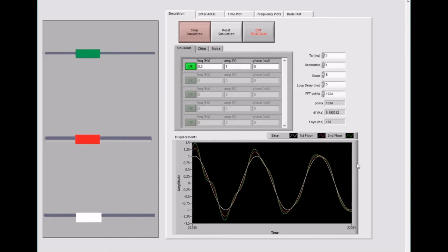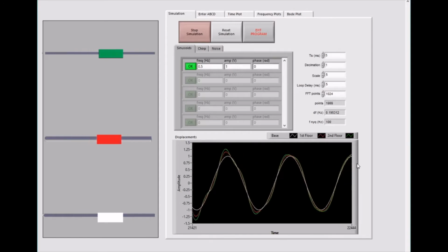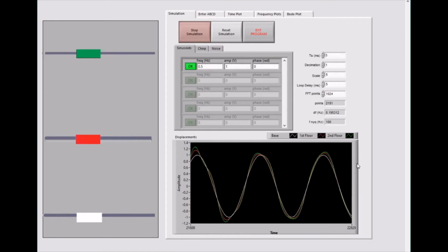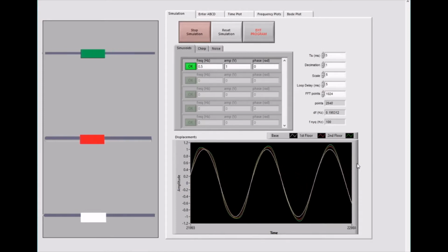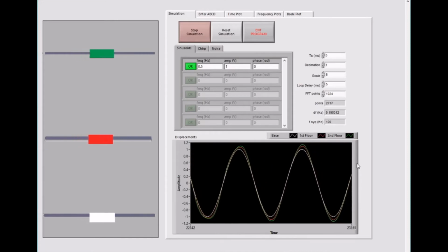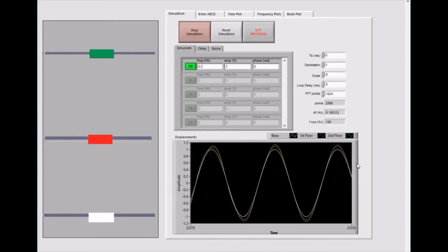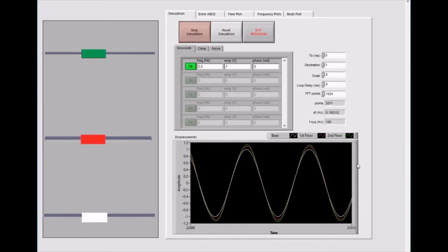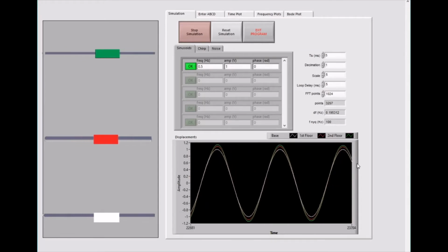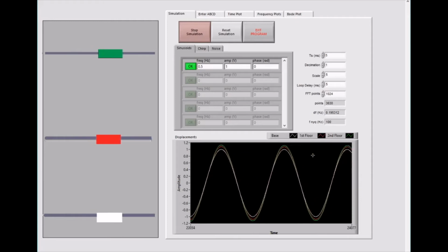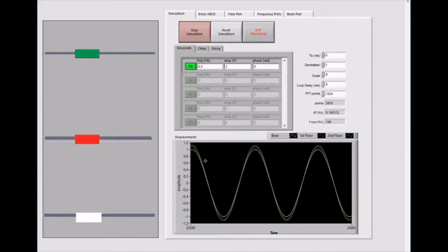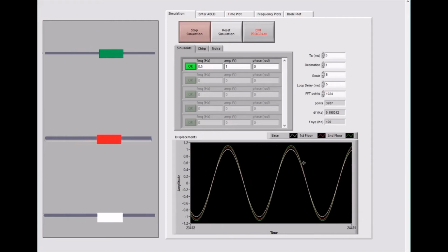So this is the response that we can see from the Bode plot. Remember, the Bode plot only has to do with the particular solution, not the homogeneous solution. All the homogeneous solutions are disappearing because it's an asymptotically stable system. So right now, this is your steady state response, the same as the particular solution.